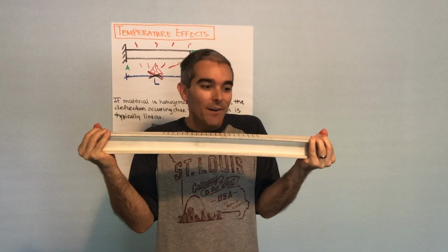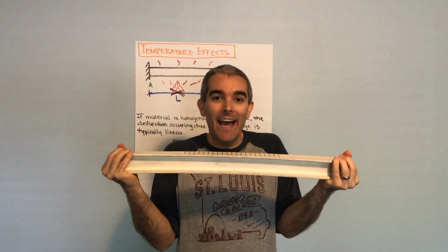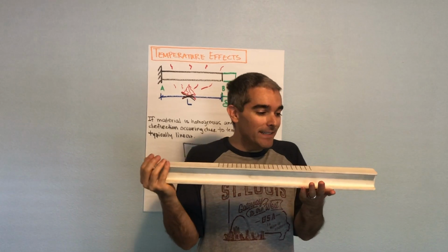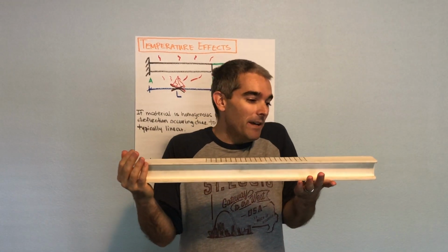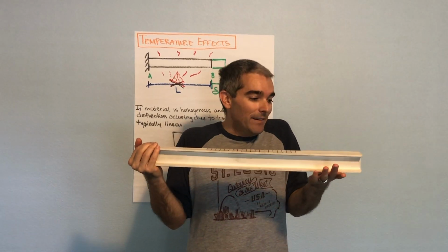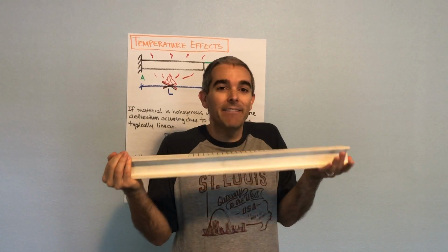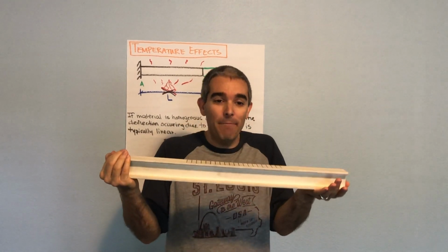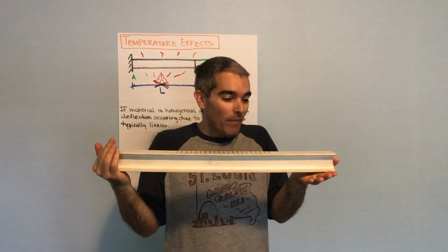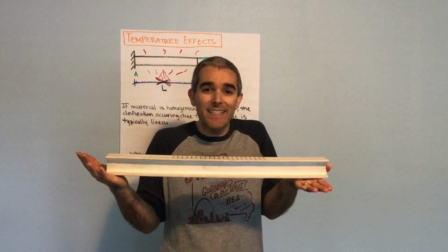Wow, our calculations told us that we developed about 9.57 KSI of compression in the member. Now, if we remember our material properties for steel, most steel beams probably have a yield stress of 50 KSI. So 9.5 KSI is almost 20% of the capacity of this beam being taken up by just the temperature change from the sun. Crazy, right? Is this something we really need to worry about when we design bridges?